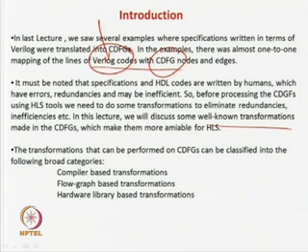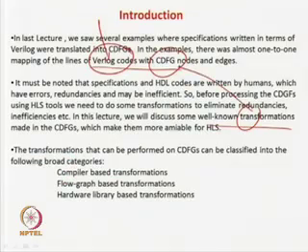So, we will transform our Verilog codes or we will transform our CDFGs, because CDFG is a formal model. So, it is very easy to see them and go for the transformations. So, you will see these well known transformations applied to CDFG. Our code will be, we should not call it bug free, because we are not catching all the bugs here. We are actually thinking that our code will be optimized. So, it will take less hardware, it will be more efficient.